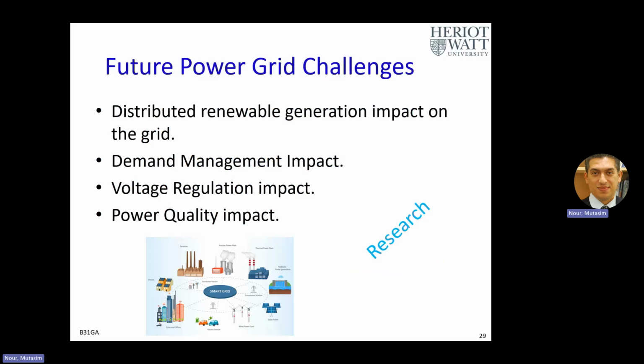What we have to do in order to make it more resilient and minimize the impact, because from renewable energy like solar, we don't have inertia for faults, for example. When we don't have the renewable energy generation, we need to come up with storage. Remember, renewable energy penetration to the grid without storage is going to be very, very challenging. Why? Because you either have to install lots of these renewables, or you have to support them with energy storage. Batteries, pumped hydro storage, flywheels, supercapacitors, and so on.